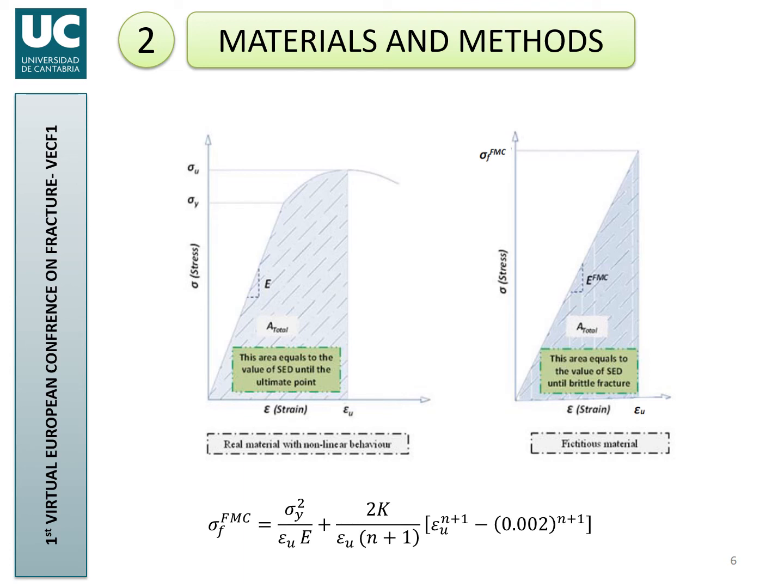The fictitious material concept is based on a modification of both the tensile and the fracture curves. In the case of the tensile curve, on the left side, you will have the tensile curve of the real material, which is clearly non-linear, and we have to substitute this behavior by the behavior on the right side, on which the shadow area is exactly the same in the two figures. The ductility is fixed, also the same.